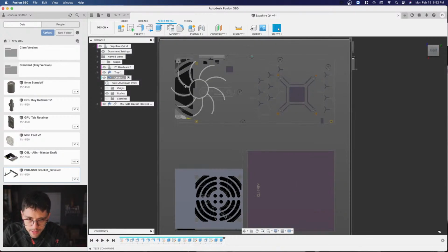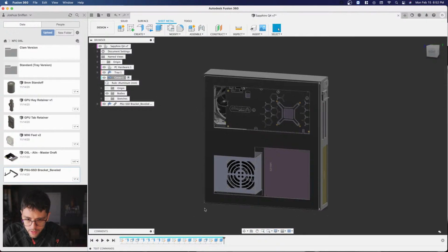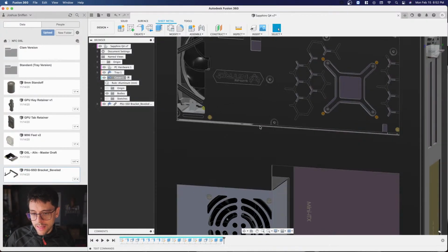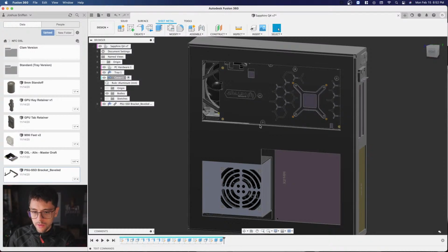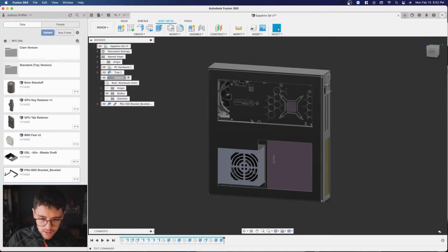And when I come back later, I'd add fillets to the sketch to smooth that out, and then put the window on top. But I think it's going to look a lot cooler now that I do that if I have this entire frame open and then make another bracket that comes up and goes over. And actually, now that I think about it, if I did it that way, I could build the anti-flex bracket right to the GPU, come over one of these holes, use an extra long M2.5 screw, and that will give it some support. So I think that's the way I'm going to roll.